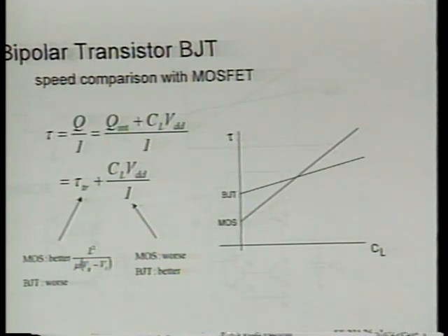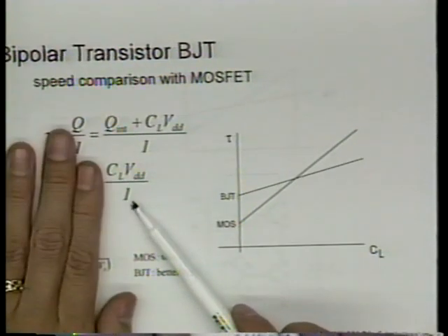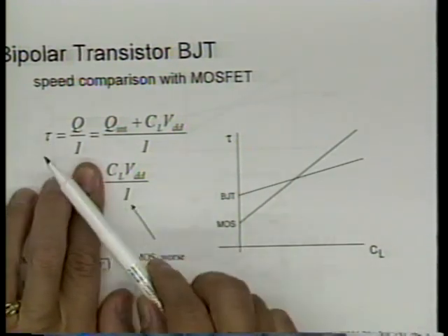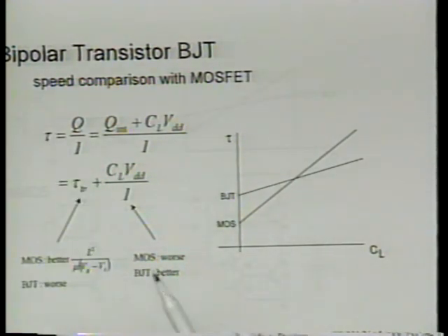All right. That is, BJT still conducts more current than the MOS transistor. Of course, MOS transistors are conducting more and more current as a result of scaling. And for the same reason, remember we said with the MOS transistor we always want I to be very large in order to improve the speed, right? But the bipolar transistor conducts even more current for a given square micron of silicon area.